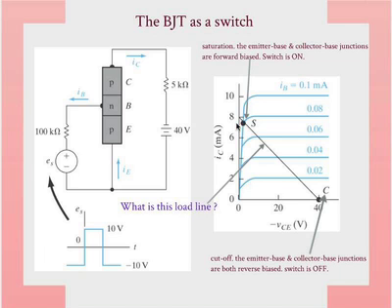Yes, so you can ignore that, approximately. So you can basically think about this as a switch which is on, with no voltage drop, so you can calculate the current. It's just V over R. So you get that point. It's approximate, it's not exact, but you get that point. And then you just draw a straight line in between.